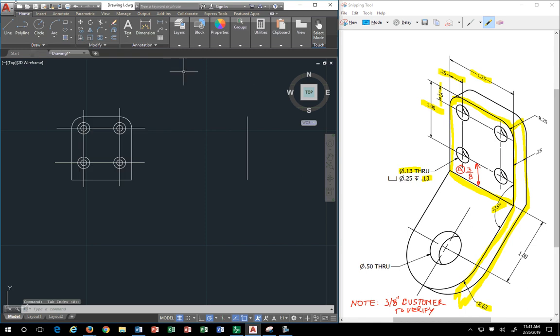When you hit OK, now when I draw a line, see that? That's 180, and I can actually increment it to what I want, which is what? 135. Now I want to go at an angle and I want to draw at the right length. What was the button that I hit on my keyboard to switch from angle to length? Right now it's on length, so it doesn't matter. The angle is good. But if I hit tab, it lets me toggle between the two dimensions. The tab, T-A-B, tab button. I'm hitting it so you can hear me hitting it. See that? That's how you toggle between the two.